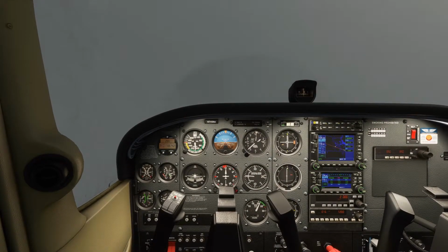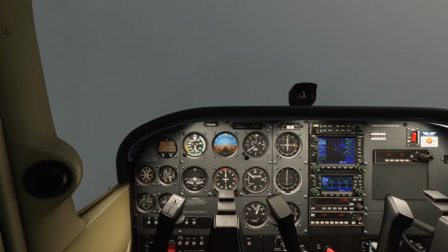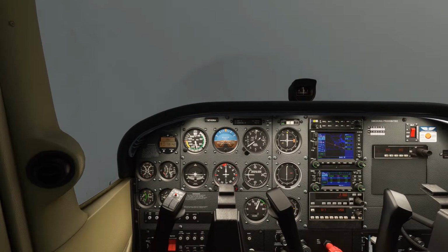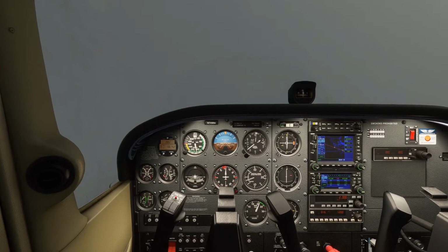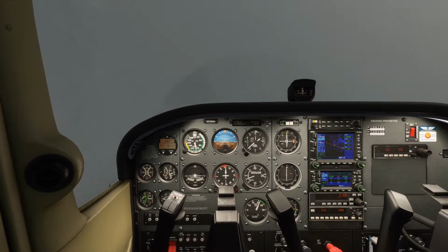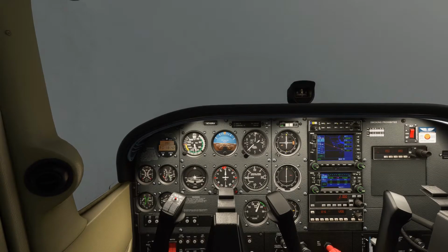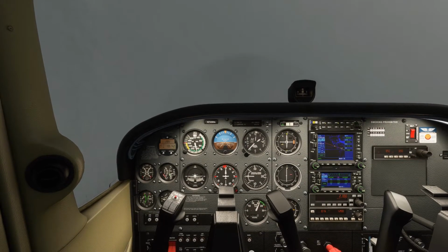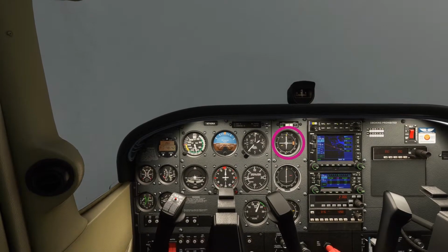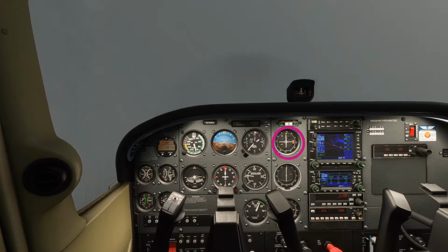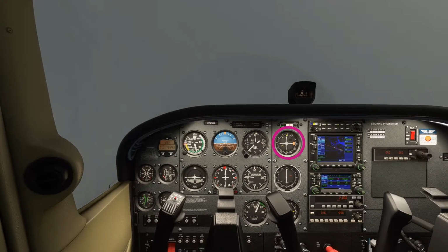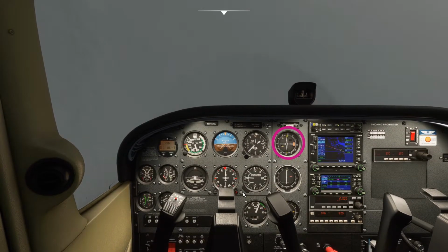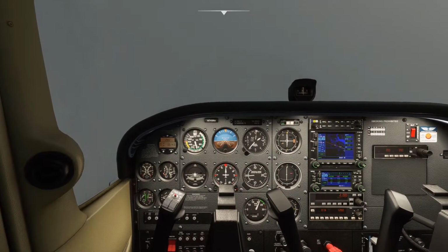There's the 1600 feet. What I'm going to do now is pitch up and just retrim the aircraft so that the speed just decreases slightly, and that way it'll mean I can configure a little bit easier for the descent. There we go. There's the CDI back in the middle, so I'm going to come to the left now to re-establish that 116 inbound course. 1.4 miles to go to Maina, so just maintaining level flight for now, correcting that heading bug slightly.